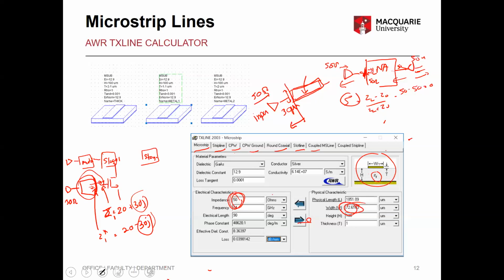When you design a matching circuit, we'll talk about this a little bit more on Smith charts in the next couple of lectures. Its primary function is to transform this 50 ohm to an impedance of that much here. The circuit you design could be a cap, then an inductor, and then a cap to ground. That circuit should do that for that particular frequency range. When I say frequency range, that's the band of interest. In your case, it's 12 to 16 gigahertz. In that band, it should transform this 50 ohm to the input impedance of the transistor.